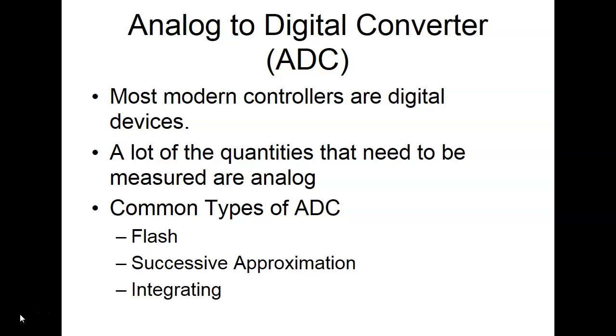Then you would have to buy an analog module for your PLC. But most of your current new PLCs come with analog capabilities. Normally it comes with analog in, and you have to get analog out. The 314s that we have, the Siemens 314 PLCs, which we'll get over and look at.